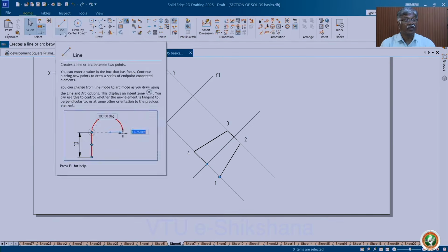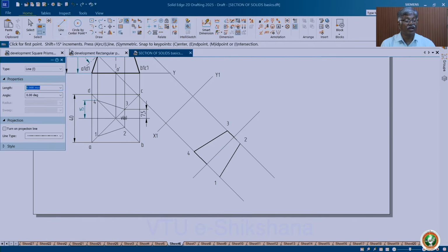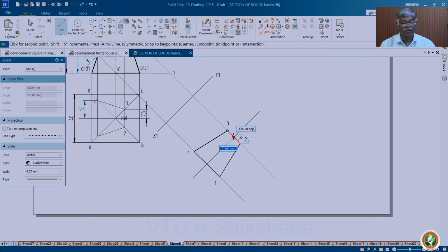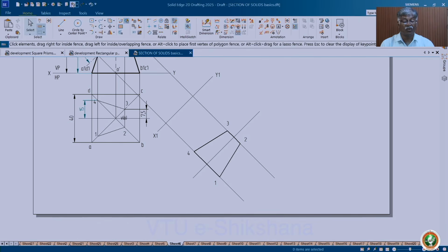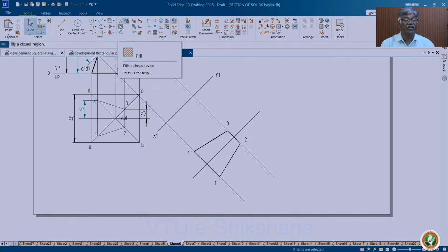Okay, redraw. Sometimes the part of it may not be this one because you have drawn earlier or later stages, then you draw again. Now, hatch this portion. See, here you are getting almost parallel because already it is inclined. Then you can change the angle. So, this is the opportunity for me to tell you how exactly you can change the pattern angle.